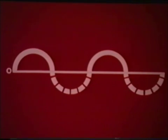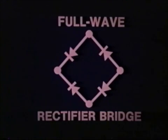A graph showing the results of half-wave rectification would look like this, with the bottom half of the sine wave clipped. This is called half-wave rectification, as only half of the sine wave is used. However, full-wave rectification is more commonly used. This schematic is an illustration of a full-wave rectification bridge.